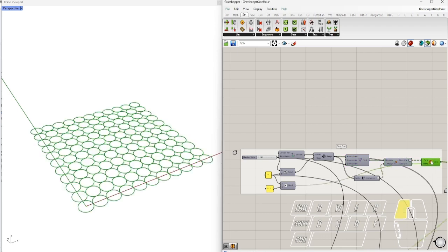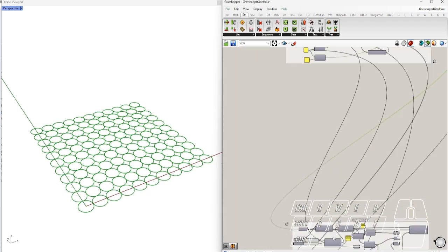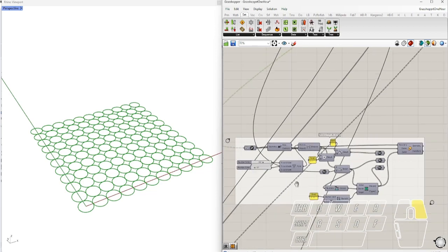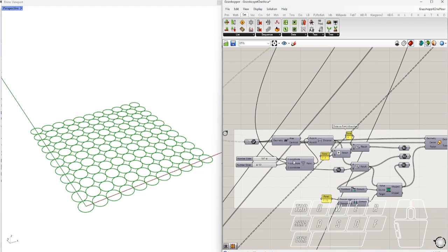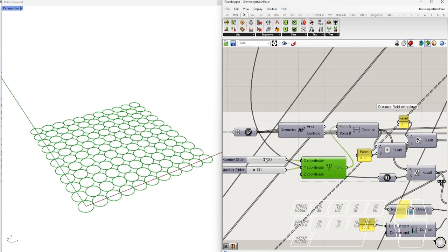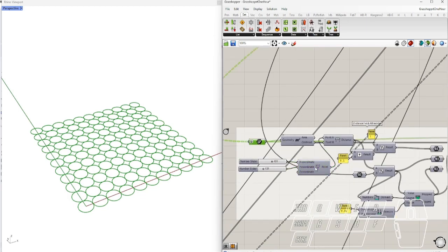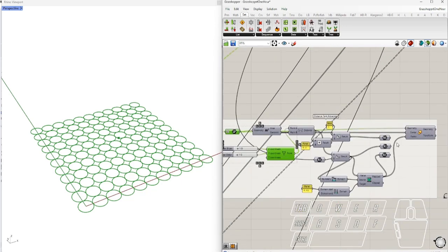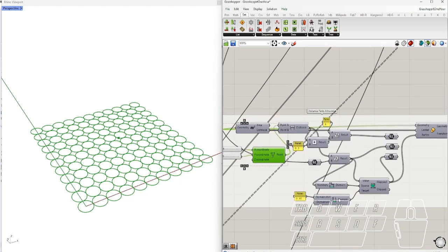to get some kind of response from a point, which I will call the attractor. The attractor is basically a point, and now it's like a distance attractor, so basically it's a distance function. It measures the distance between the attractor point and the centers of each one of these circles, and tries to make them smaller or larger according to how close or far they are from this point. And I'll make sure that they won't get messy and get intersected. Let's check that out together.